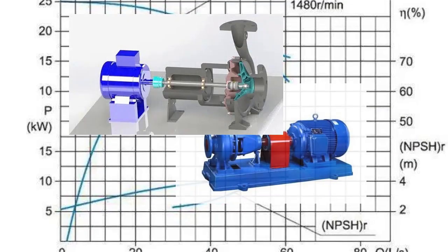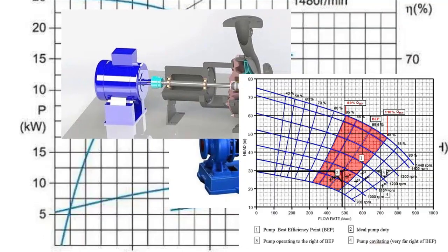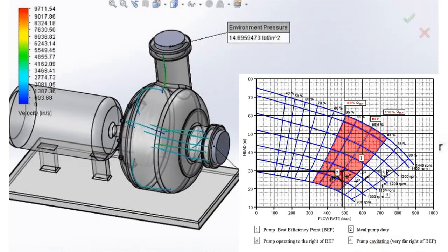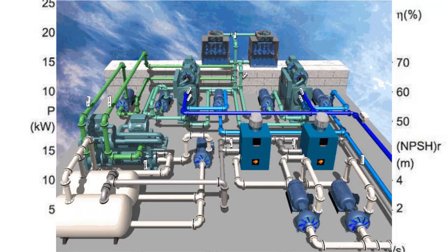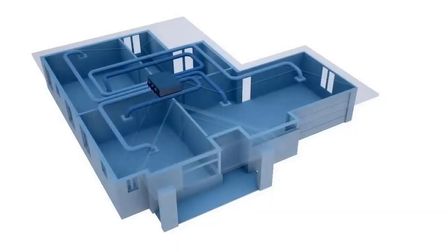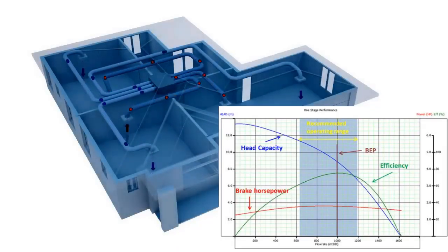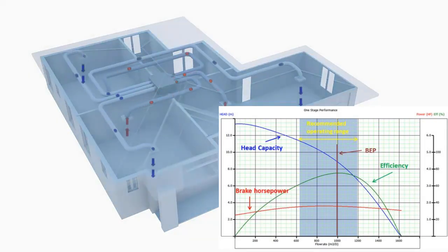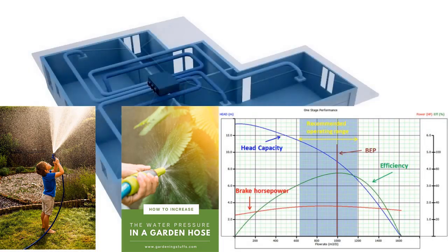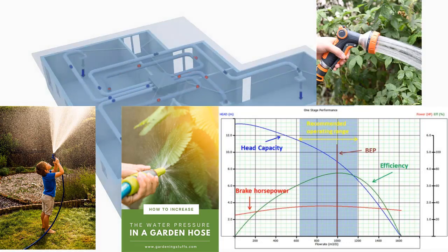The first thing I must say is that more pressure does not mean more flow. I get calls from clients all the time saying they aren't getting adequate cooling from a chiller, but there's great pressure, so the problem isn't the flow. I take a deep breath, bite my lip, and then proceed to talk about pump performance curves and give them a simple analogy. If you have a garden hose and squeeze the end of the hose, the pressure builds up in the hose. You get higher pressure before the point of the squeeze, but you are reducing the flow rate coming out of the hose.